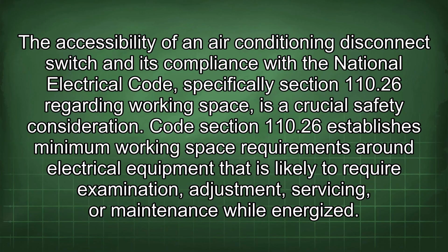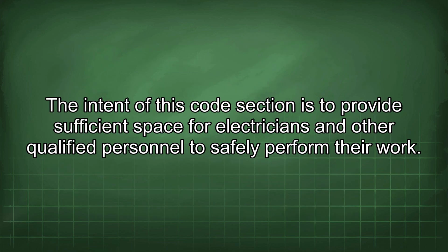The accessibility of an air conditioning disconnect switch and its compliance with the National Electrical Code, specifically Section 110.26 regarding working space, is a crucial safety consideration. Code Section 110.26 establishes minimum working space requirements around electrical equipment that is likely to require examination, adjustment, servicing, or maintenance while energized. The intent of this code section is to provide sufficient space for electricians and other qualified personnel to safely